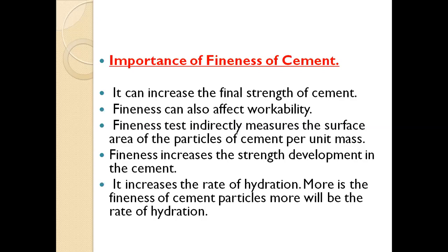So more fine cement will give early strength, or more strength in early days. Also, more fineness leads to more surface area, due to which it contacts the water and increases the rate of hydration.